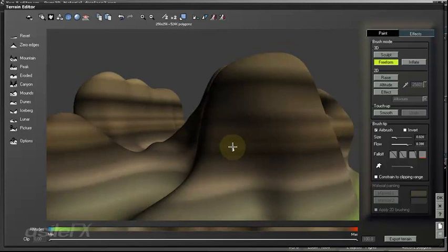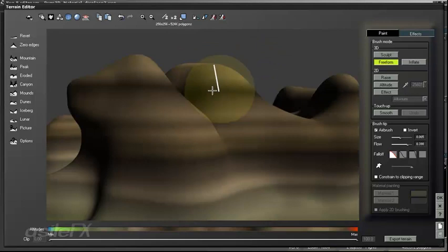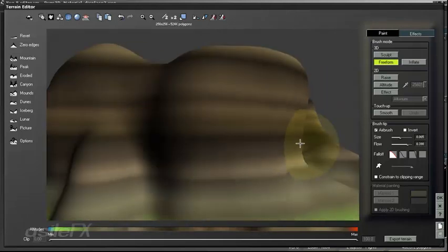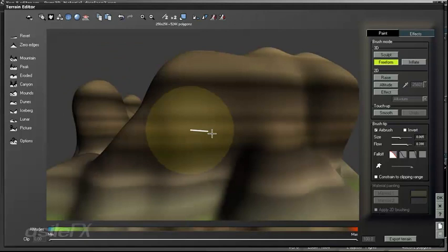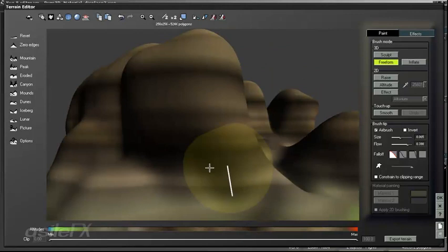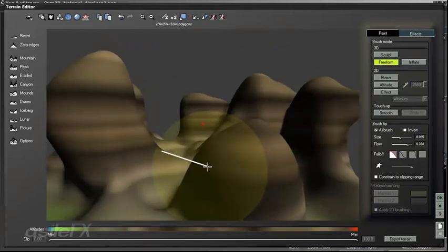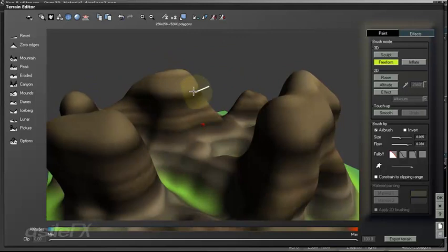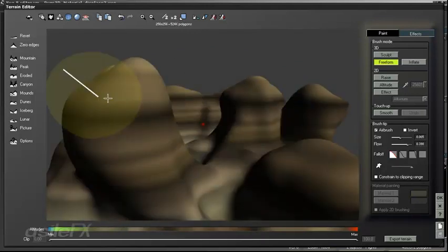We can then switch our filter and begin sculpting some of the finer details and giving us a little more of an interesting terrain, which can be used directly as a displacement or to eventually reach the point which we'll be at eventually once we bake the terrain. But making all of these steps first is very important, because once the terrain is baked, it is no longer a terrain object and just a mesh.